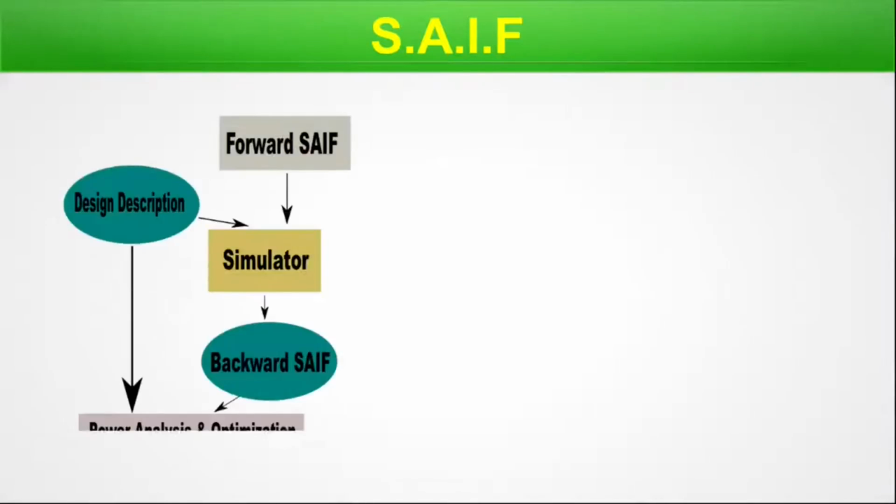Let's move on. Power switching vectors are very important in the sense that they define the power up or power down sequence. This switching activity must be coherent between the UPF and the HDL, such as Verilog or VHDL. Hence, the SAIF has come into the picture. Let us understand this in this slide. So let me bring my mouse pointer here. We'll define this by text descriptions. But the simulator is able to generate the SAIF and we can use it to back-annotate again in power analysis.